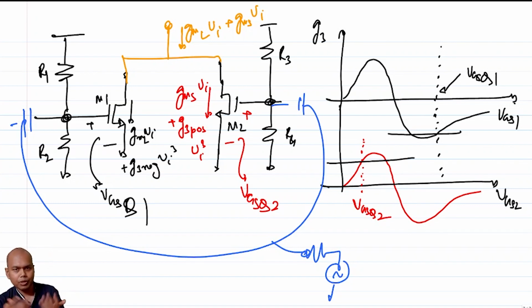It's not possible for me to cover everything, but hopefully you got a flavor of how to go about designing an LNA in order to ensure that not only do you honor matching, get gain and reduce noise, but also simultaneously use mechanisms to reduce distortion.